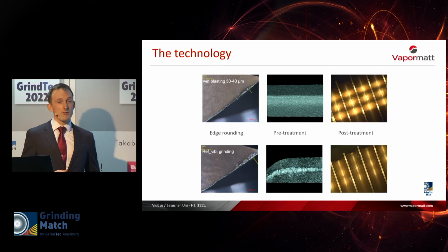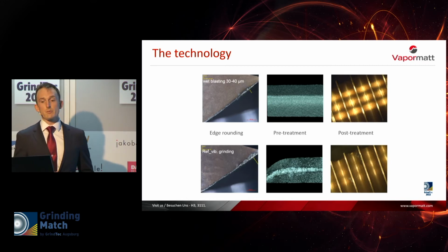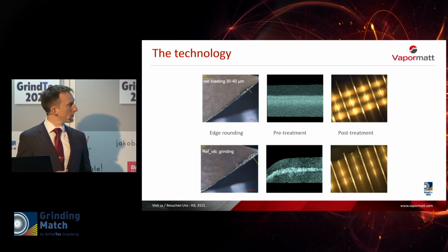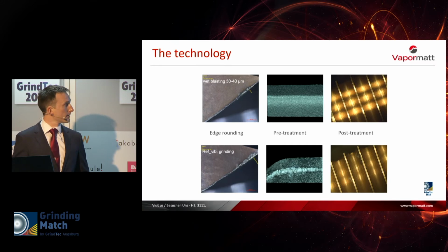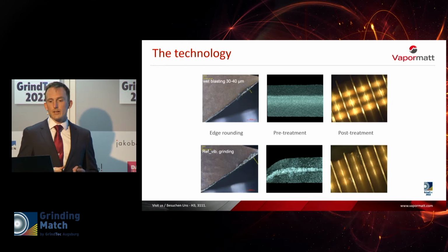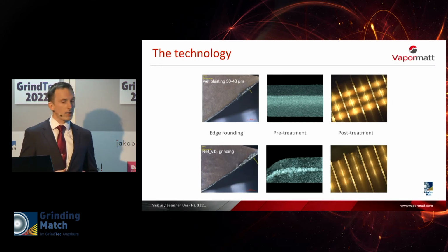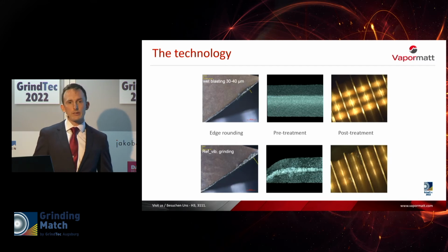These benefits can only be realized if and when the correct abrasive is being used. And in order to do that, we have to understand the shape, the size, hardness, and density of the particles that are going into the machines. Failure to get the abrasive correct can lead to much wider tolerances on the parts and slower processes, ultimately leading to poorer quality tools.